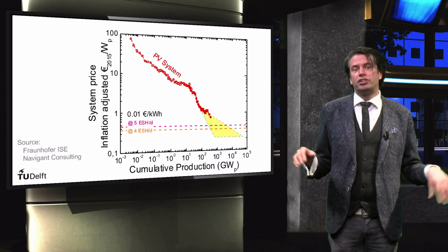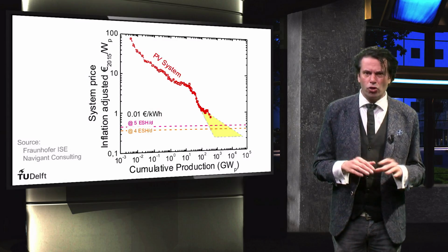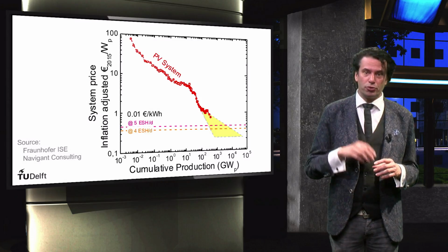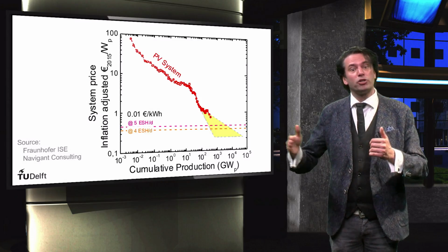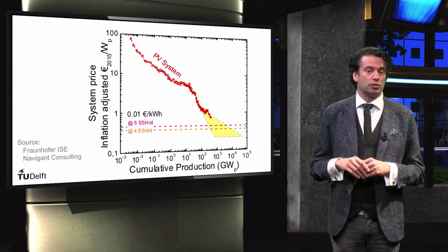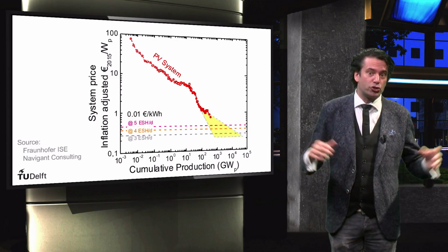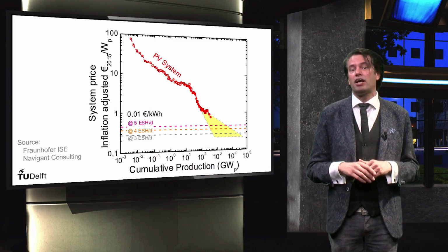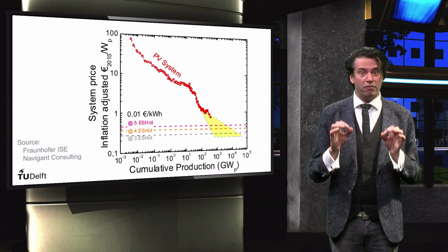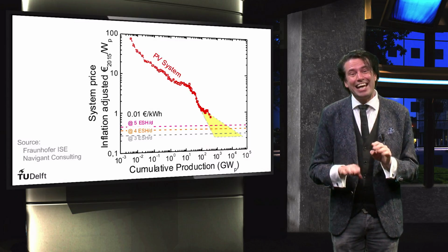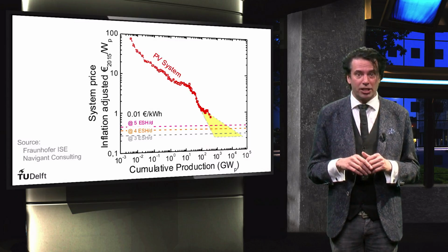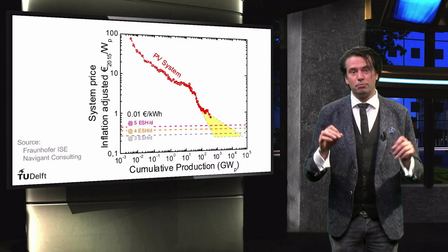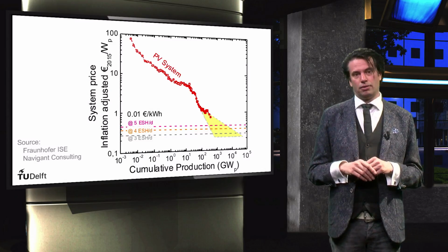In climates with on average a daily irradiance of 4 equivalent sun hours, the cost price of the PV system has to be 37 euro cents per watt peak to realize the 1 euro cent per kilowatt hour. It would take an even much longer time to reach this milestone in these regions. And let's consider regions in the northern or southern hemisphere at higher latitudes, and let's assume they have an average daily irradiance of only 3 equivalent sun hours. The cost price of the PV system would need to drop to 28 euro cents per watt peak to meet the 1 euro cent per kilowatt hour magic boundary. It would take an even longer time to reach such a milestone in these places.